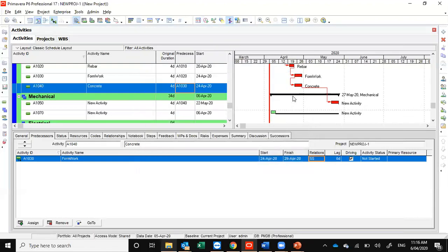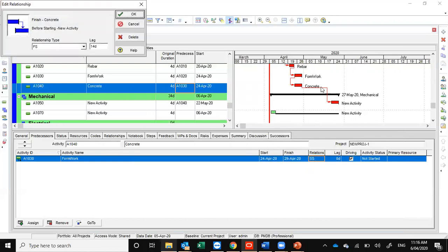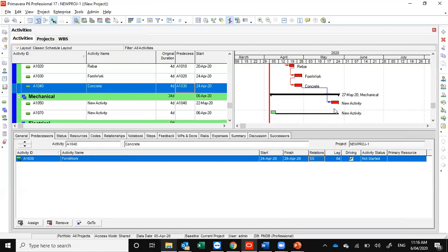Okay. So this is the set of steps you have to follow to make relationships in Primavera, and every time, whatever changes we make in relations and whatever logic we make, we always have to reschedule to reflect the changes. We even have an option for customizing the relationship from this line of relation. Like the shortcut, it's very easy to do the lagging and types of relation changes here. Okay. So further we'll continue with CPM.